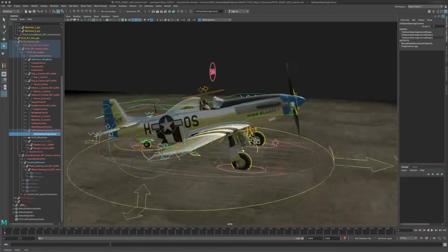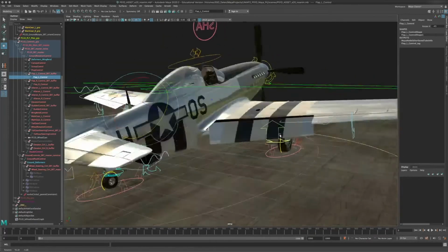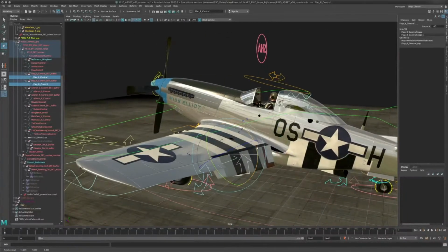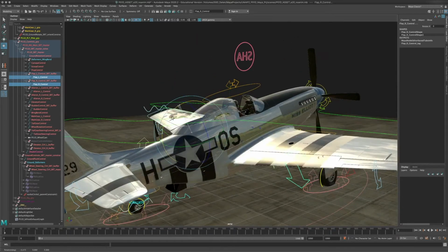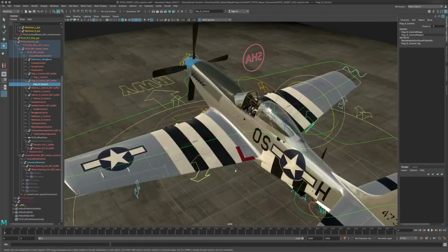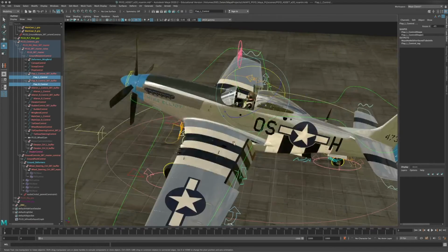So one thing that would not be extended on takeoff are the flaps. They can be selected and moved. Take the flap control. I didn't implement the fact that they are moving in parallel, so you have to select both and move both up. Normally you would.